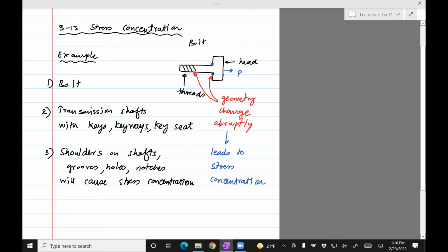The method which people use is a technique called photoelasticity, which is basically making a specimen of plexiglass. Maybe it's not plexiglass, it's a translucent material, and then they load it, and you get nice fringe patterns, and those fringe patterns tell you something about the loading. They use the same thing to design landing gears for planes. Anything which they expect is going to have stress is going to be tested with photoelasticity, not using finite element. But finite element is a good way to get started.